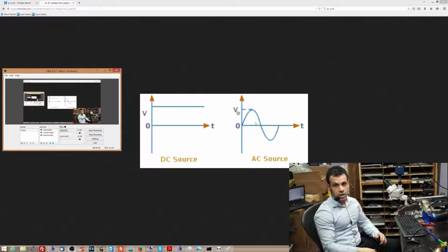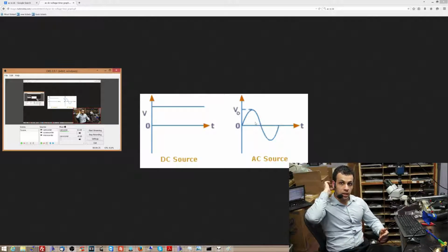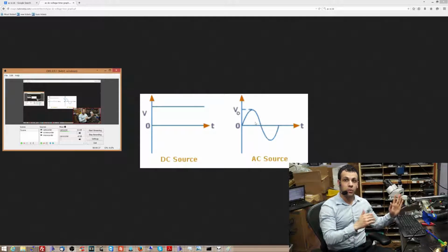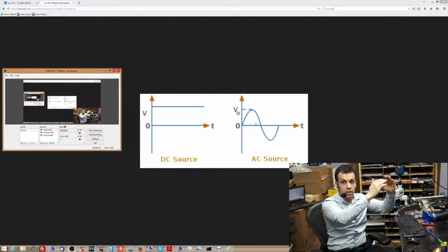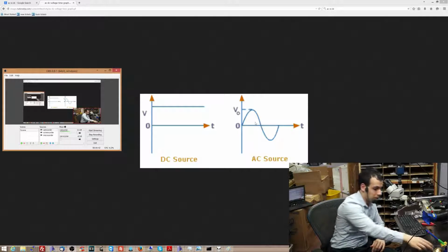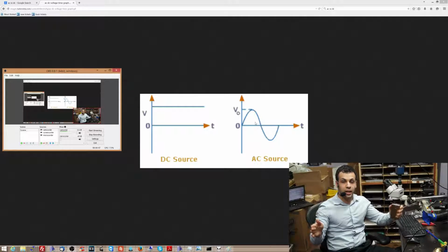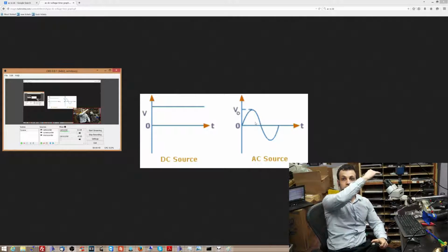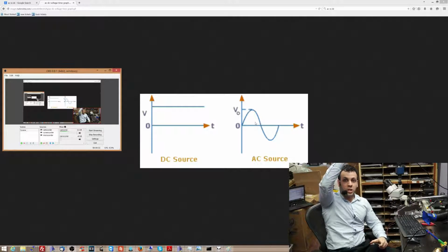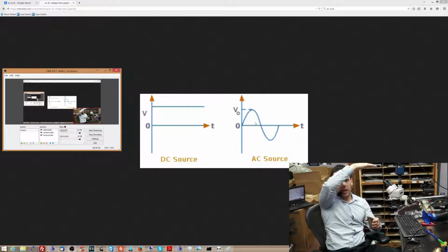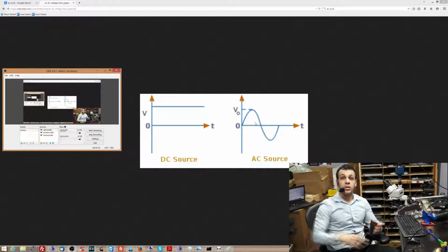Now, the same thing can be said for, let's say, a musical amplifier. So my amplifier down here, the way it works is you take an input signal, and then it wants to modify a bigger signal to create the output signal. So let's say I take the tiny signal out of my cell phone, I plug it into the amp, and then I get a big signal out of the speakers. What it's doing is it's taking a really high power level, and it's modulating that high power level based on the tiny one. So it's turning this high power, like let's say 70 or 80 volts, into a waveform for my speakers based on the 0.5 or 1 volts that comes out of here.